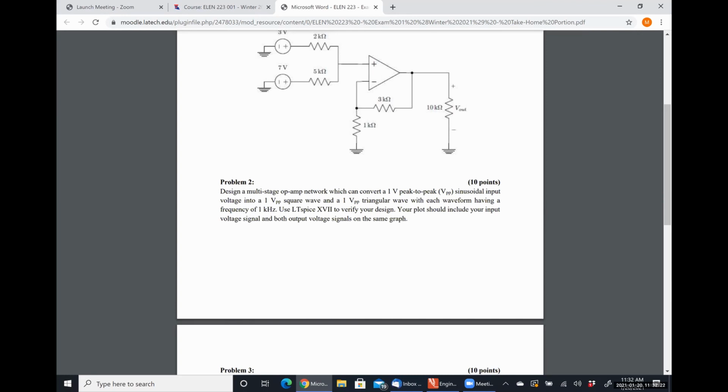I don't know what you mean by half to half there. You're not going to see an exponential response because you're not looking at a transient here. So it should be fairly linear. I mean, there might be a small curvature, but it should be a fairly linear triangular wave where, I don't remember off the top of my head if you're going to wind up with a DC offset or not, but it should be something like,